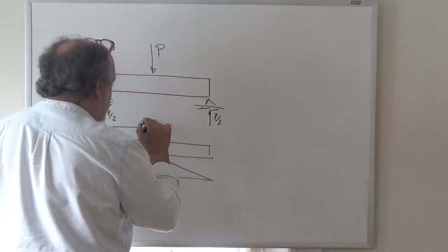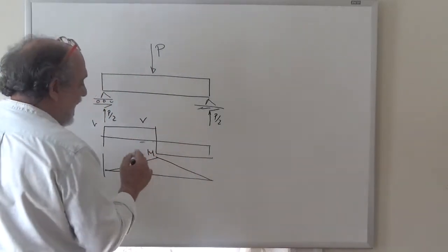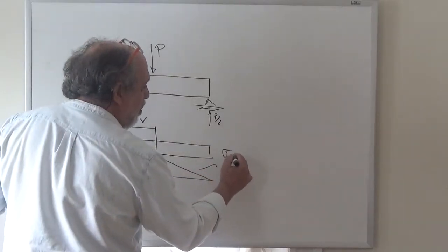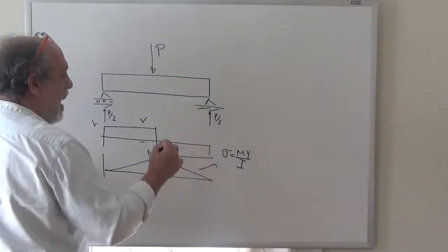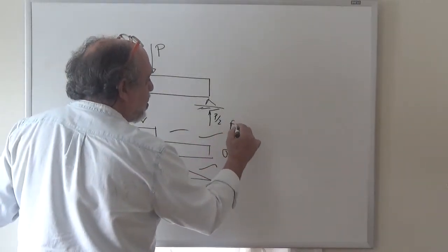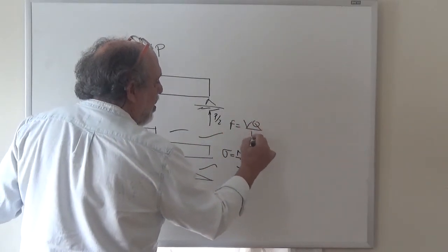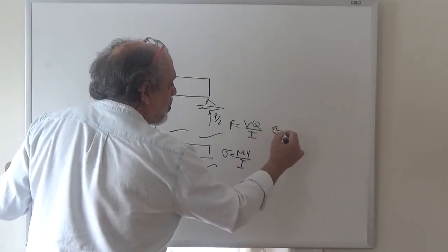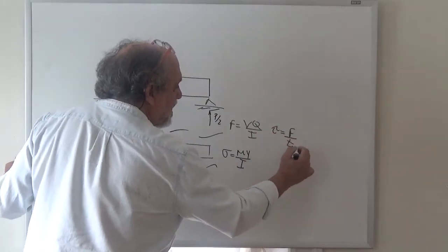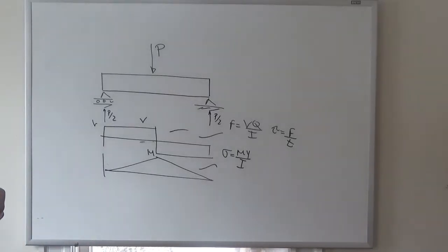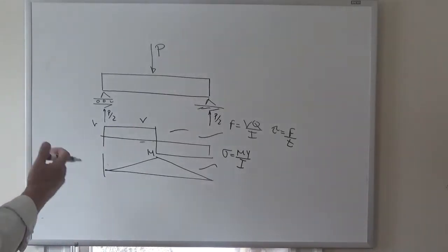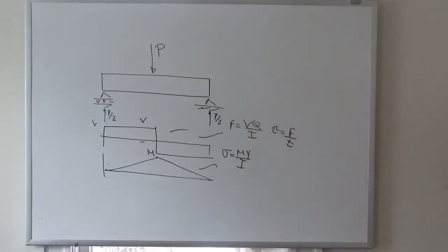And once I have my shear and my moments, I can calculate my stresses from My over I, right? I can calculate my shear flows as VQ over I, from where I can calculate my shear stresses as the shear flow over thickness. I can do everything, right? And it's just from statics. Well, not really. You can do everything that we normally do most of the time, but that doesn't mean that